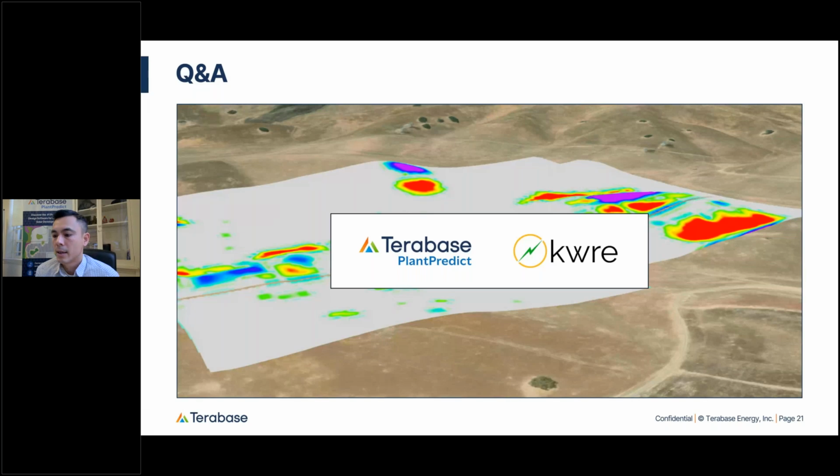So yes, the array layouts from tracker suppliers that we've seen quite a few of are actually great as an input for this process. Actually, they are the inspiration for how we've structured this workflow. They often are structured exactly the way we need, which is having piles as nested blocks within the tracker blocks. So this is a great way to start your earthwork analysis, because that's the best way to get where the piles are going to be located, the specific pile spacing for your tracker for your site.